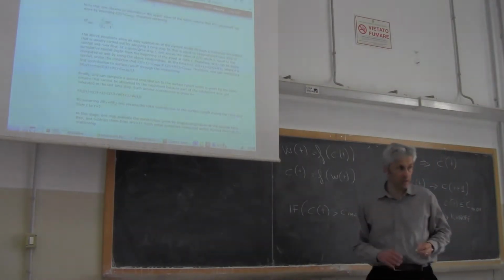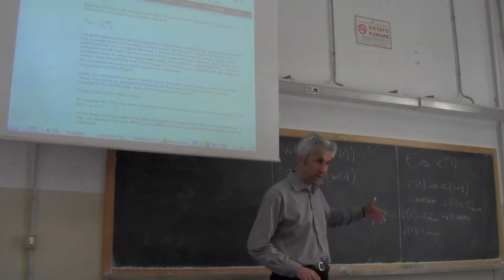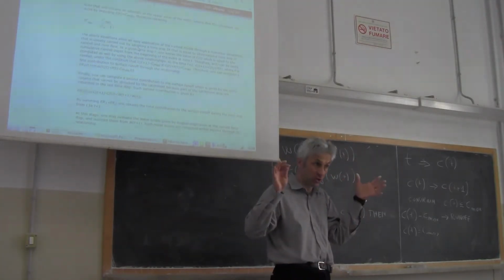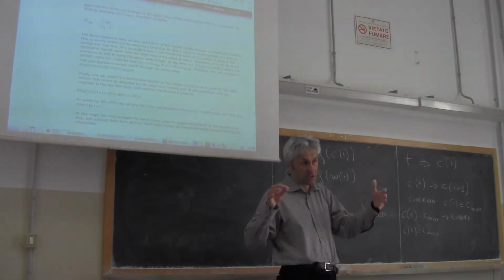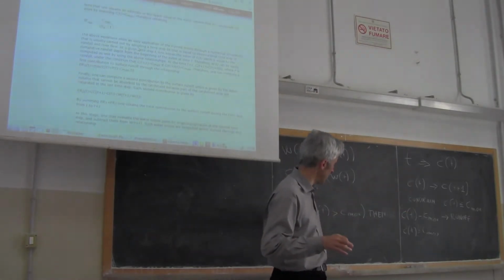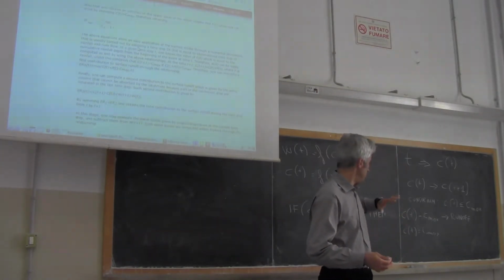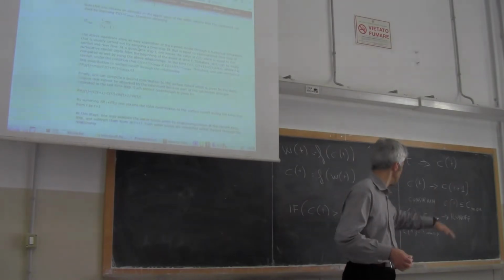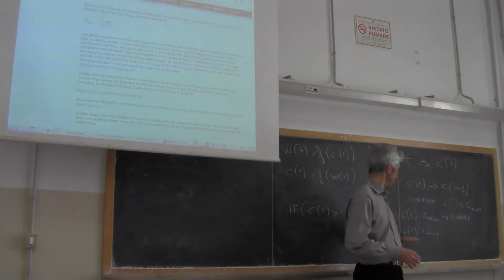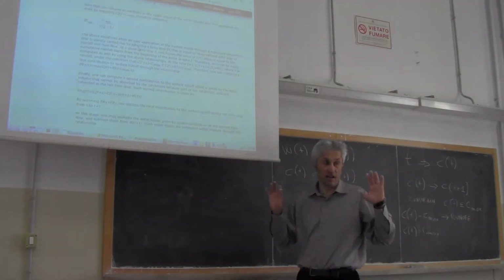So my algorithm should establish this condition. If storage Ct becomes higher than Cmax, this is not possible by definition, because it cannot be that in any point of the catchment more water is stored than the maximum possible storage. Therefore I have to do two things. First, tell the PC that the amount of Ct that exceeds Cmax, Ct minus Cmax, is transformed into runoff. And second, Ct is set equal to Cmax, because it cannot be higher.